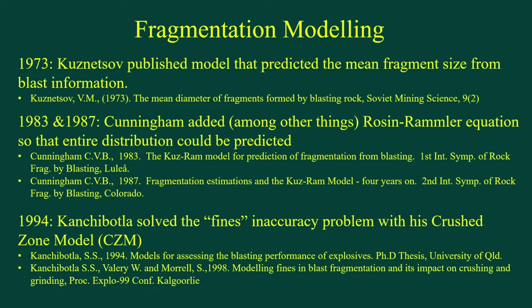I've chosen three landmarks, I suppose one could call them, where significant advances were made, and we need to go back to 1973 for the first one, where a Russian man called Kuznetsov published this paper here, and he put together a model that took various blast information and predicted the mean fragment size from that information.